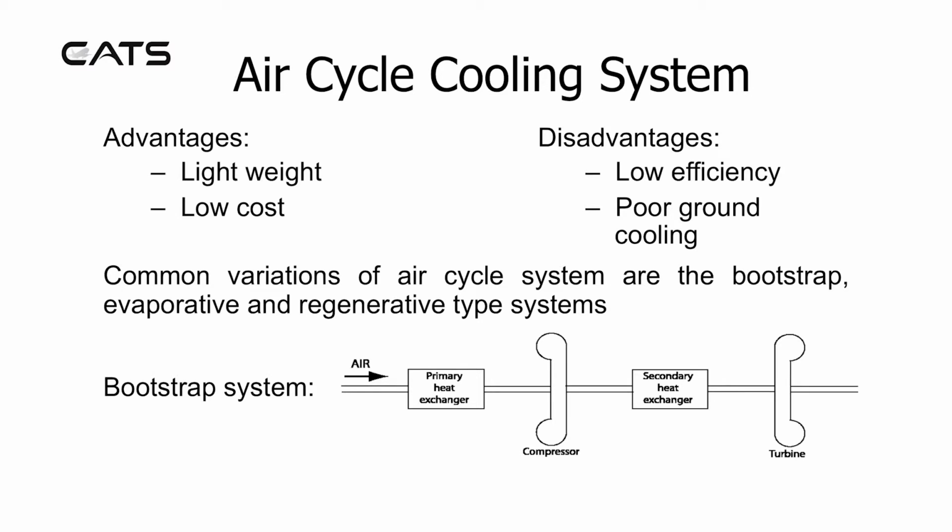The advantages of the air cycle cooling system are: it's lightweight and low cost. The disadvantages are low efficiency and poor ground cooling. Common variations of the air cycle system are the bootstrap, evaporative and regenerative type systems.